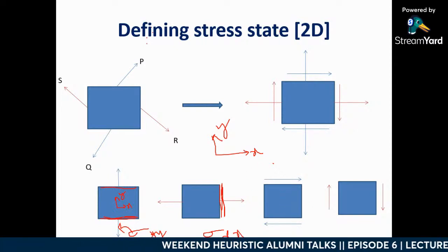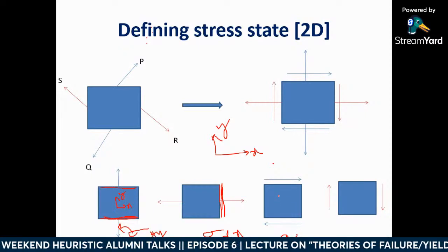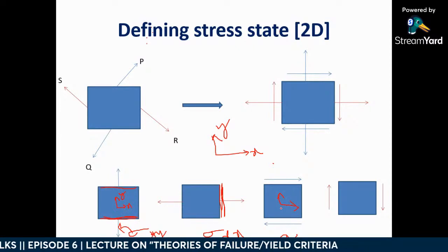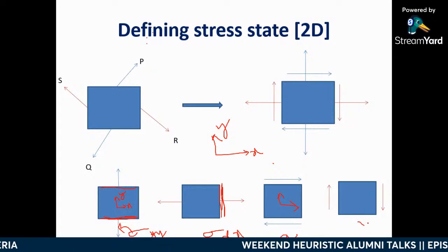Similarly, here it is a shear stress. On which plane is it acting, the X plane or the Y plane? It is perpendicular to Y, right? So it is the Y plane. And what is the direction of the stress? X, right? So it is tau YX. Like this, you can give the naming for this stress component.